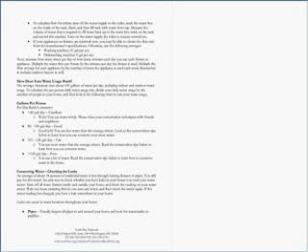You can also measure the amount of water used by all your appliances, such as washing machines and dishwashers. Flow rates are usually on the manufacturer's specifications. Otherwise, we provided some averages. And then finally, you're going to want to measure how many times per day and how many minutes each day each fixture or appliance is used. You multiply by the flow rate to calculate the daily or weekly average.